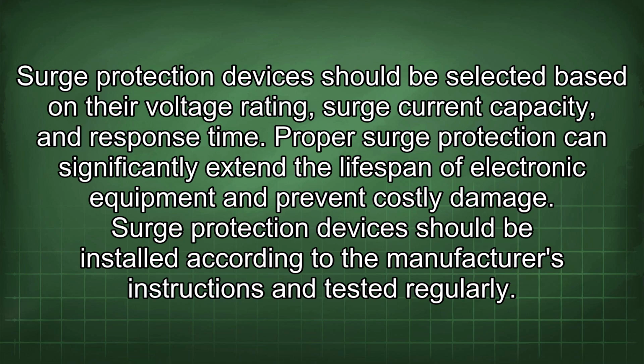Surge protection devices should be selected based on their voltage rating, surge current capacity, and response time. Proper surge protection can significantly extend the lifespan of electronic equipment and prevent costly damage. Surge protection devices should be installed according to the manufacturer's instructions and tested regularly.